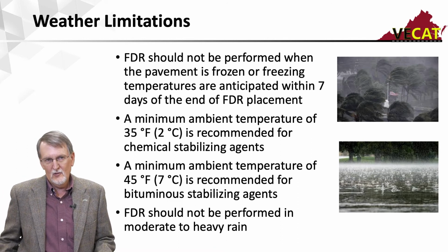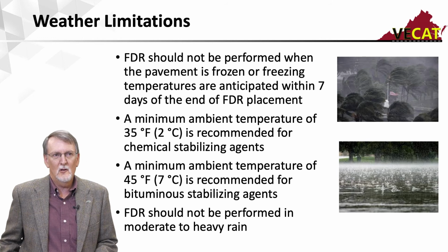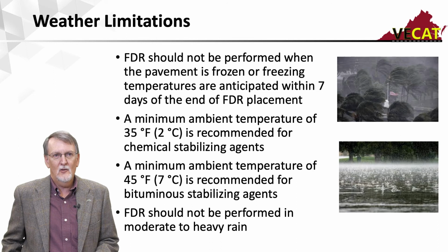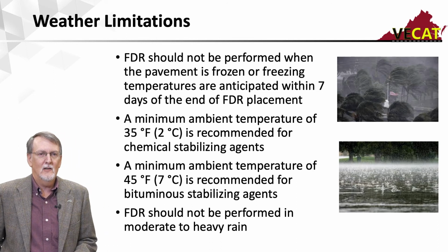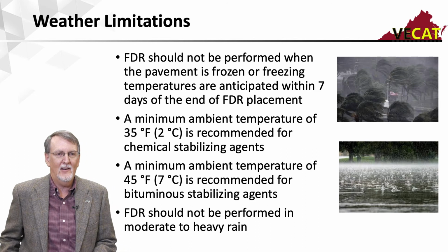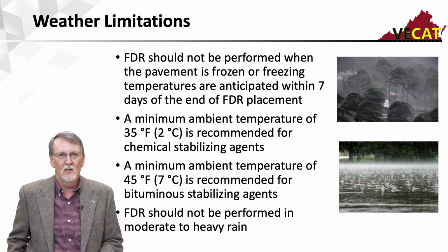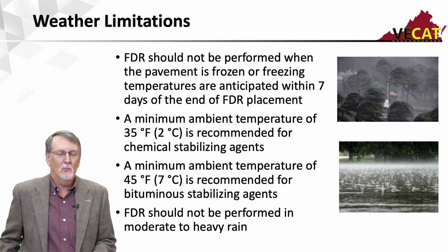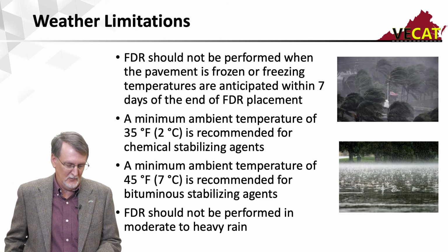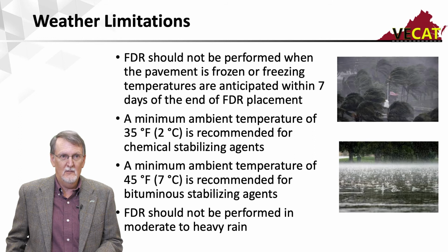With the bituminous, it's typically 40 to 45 degrees and rising. And FDR should not be performed in moderate to heavy rain. Realize we are adding moisture to this mix with compaction. So if we're getting light rain, and as long as we're not spreading a dry chemical agent, a light rain's not particularly going to hurt us. But we want to watch out for heavy downpours.